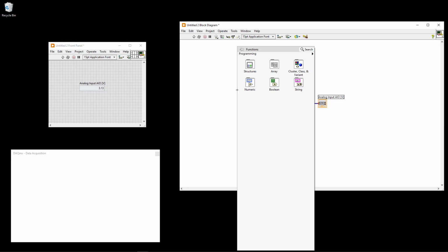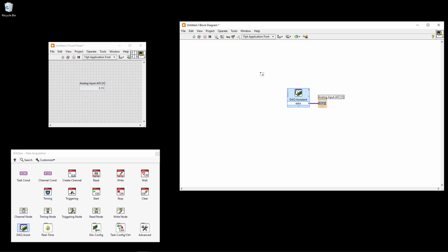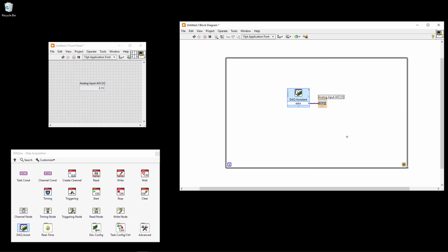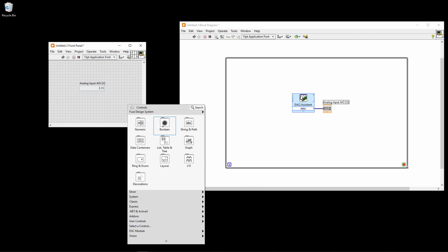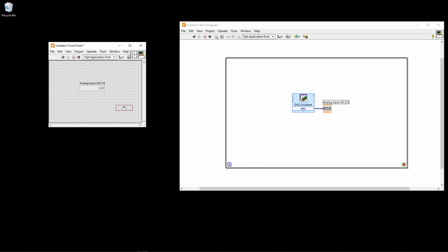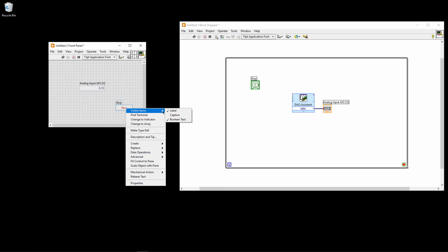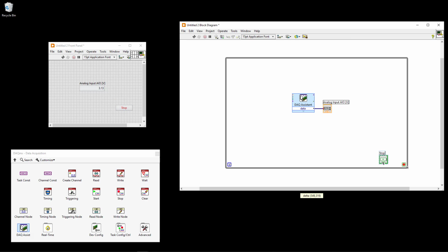And then next step, typically you of course want to have this in a loop. It's not so important for the battery package of course, but if you connect a sensor or a variable source instead, you typically want to have it inside a while loop. And then you also typically need a stop button for your program, which you wire to the loop condition here in the bottom.